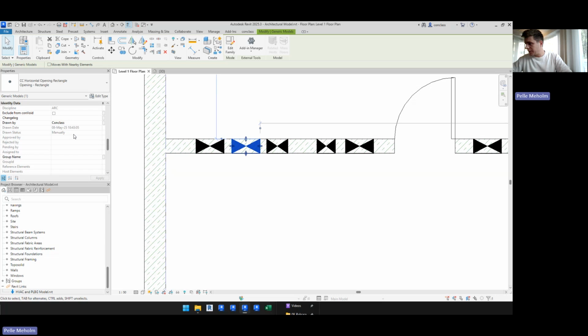When the MEP engineer changes a rejected opening, does he have to modify the openings manually or run the tool again? You probably saw that case. They changed the location of the pipes, reran ConVoid, and the openings got changed automatically. But of course, you could also do the change manually. That would also be possible. But we would recommend, if it's possible, to do it automatically.